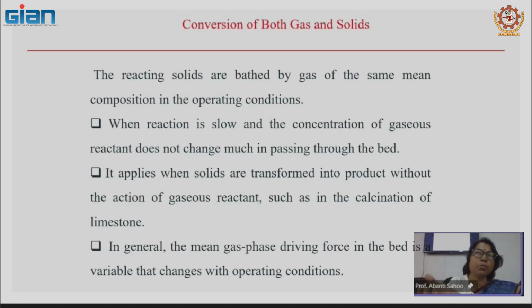During that movement towards the top of the bed, the reaction does not take place much; only slight changes will be there. First, when the cloud is formed, the cloud is the gaseous reactant clouding the solid reactant, which will try to diffuse into it, whether it is porous or non-porous.